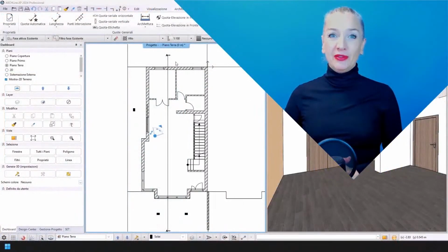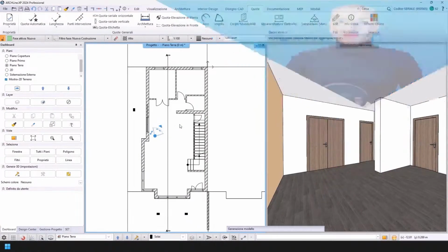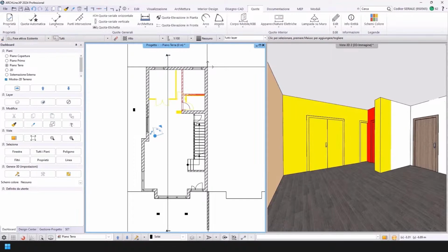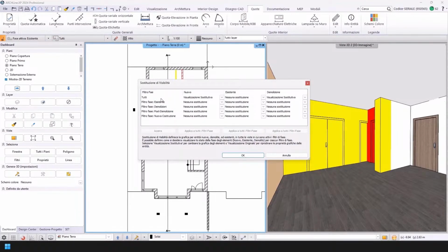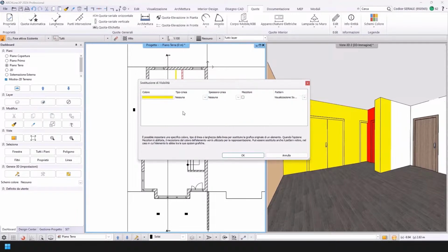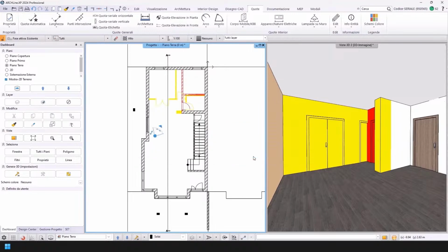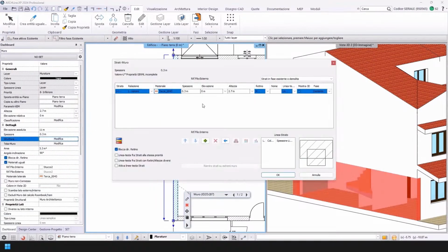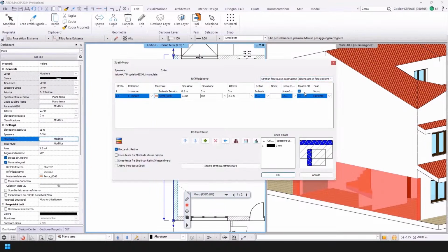In this part of the video, I show you how to work on an existing building in ARCHLine.XP. ARCHLine.XP has two features that allow you to design a building structure in multiple phases and document it later. The first is phasing, which is native in the floor plan design. In fact, among the properties, there is a phase property thanks to which I can adjust the visibility of the element and also the recoloring or graphic overwriting.